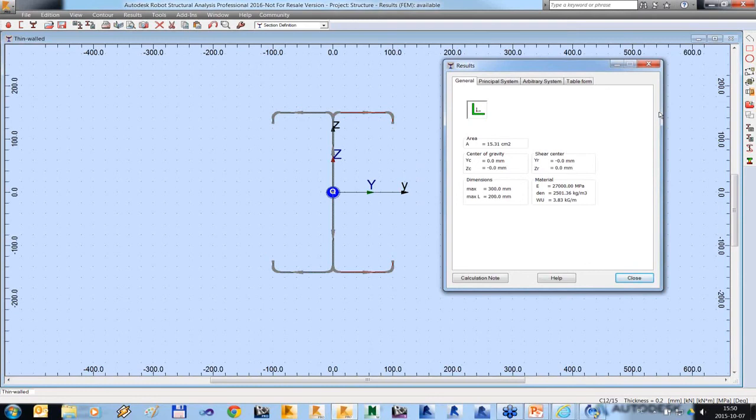Yeah, there was a question about box sections with additional flanges and how this is recognized in the steel design module. So basically the rule is that after you created the shape of the section and calculated its properties, you assign the section type as was shown during the presentation. And this selection determines two things.